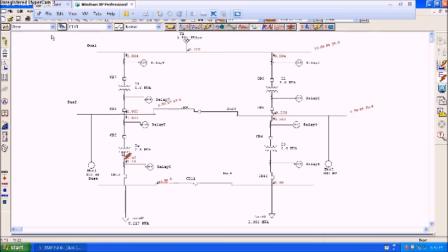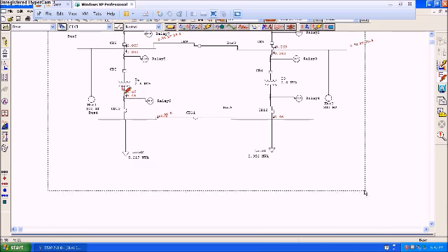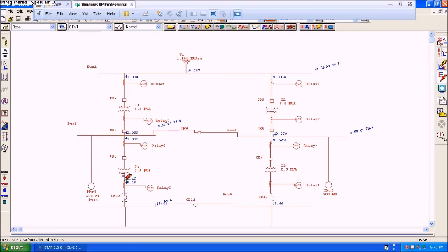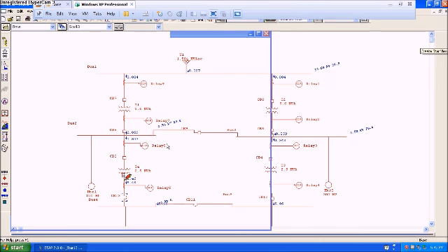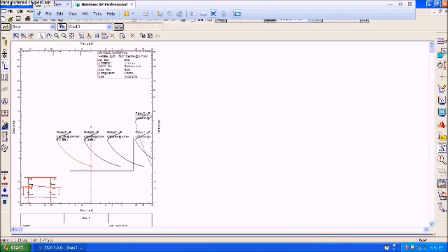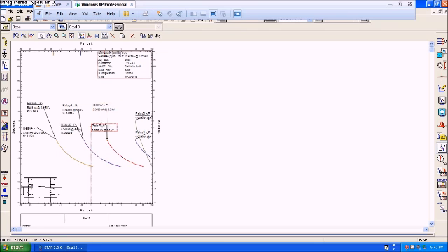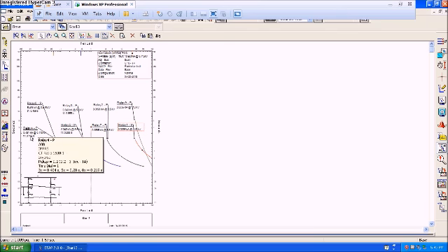Now we will show you this in the circuit and explain our concept. So we can bring our circuit from here. You can see the operating times of two relays are the same, which are 6 and 4, and at the same time the time settings of relay 5 and 3 will be the same.